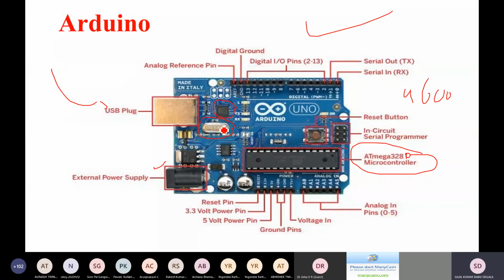It is a 16 megahertz oscillator, and if you want to utilize this Arduino board more effectively, we suggest that you use it at a 9600 baud rate. So 9600 is a perfect baud rate for this Arduino board. It may work at a higher or lower baud rate, but you are not going to utilize the board completely, and sometimes you may get errors.